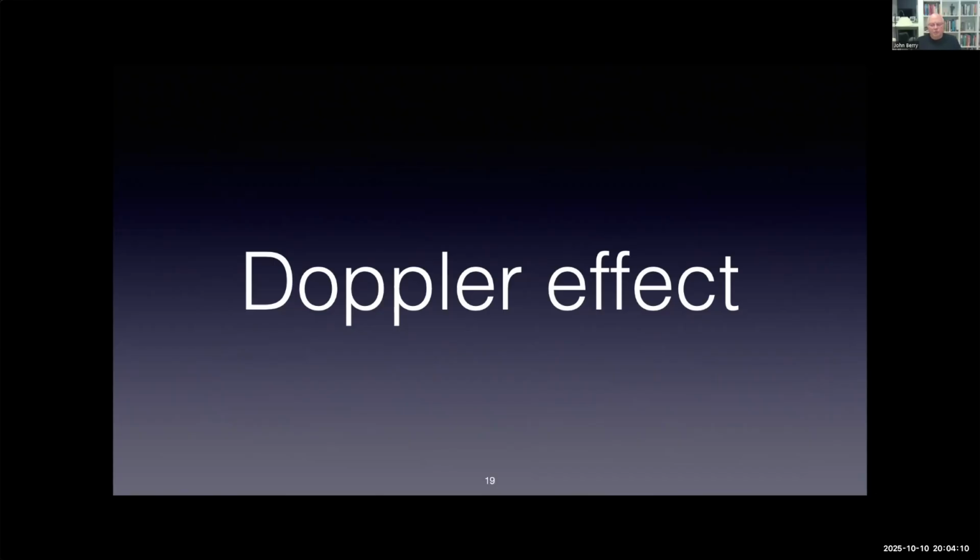Now, everybody knows the Doppler effect. Police car comes towards you, siren on. As it comes towards you, the pitch rises. As it goes past you, the pitch falls. And that's exactly what you heard in that GP3NI clip at the very, very beginning. So we do need to consider and think about Doppler. Doppler will play havoc with FT8, and FT8 may be pretty useless in the case of this effect. So that's why Q65 is so good, and we'll see that.